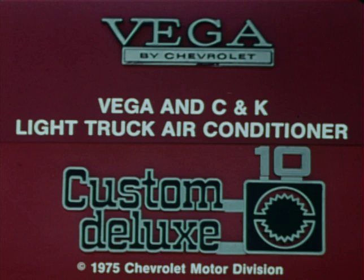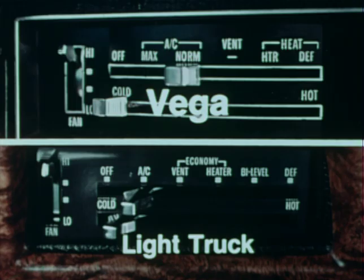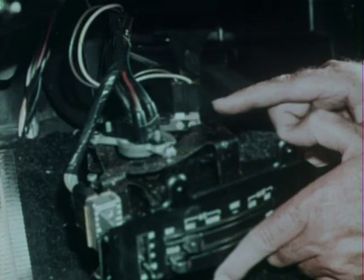In this program, we will review the operation of the OTCC system and some diagnostic procedures that are unique to it. The Vega and the C and K series light trucks use different control panels with some differences in air distribution. The operation of the system is governed by two levers and a switch located on the control panel. The upper lever is the selector lever, the lower lever is the temperature control lever, and the switch at the left controls the fan speed.